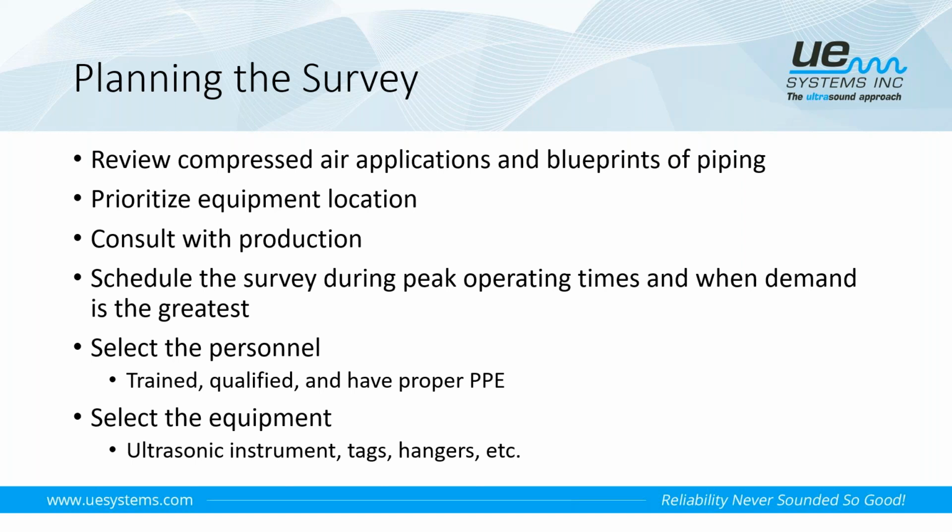Consult with production. We want to make sure that they're aware of what it is that we're doing. If they see us walking around out on the plant floor, around the machines, we want to make sure that they're aware that we're conducting a compressed air leak survey. And we want to make sure that we do the survey during peak operating times. Again, we're not really concerned about plant or ambient background noise, but we want to make sure that we do the leaks under normal operating conditions. And typically that's going to be during those peak operating times.